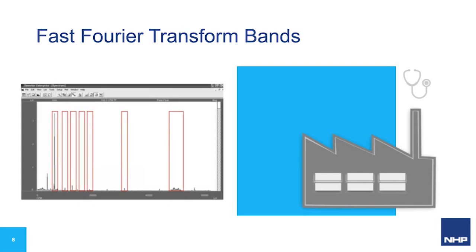Now that we're looking at a spectrum, essentially just a 2D view of the right-hand side of the 3D drawing that we showed earlier, each FFT window indicates the vibration magnitude for a specific frequency range of a measured accelerometer signal at a single point on a machine. So the displayed bands, or frequency windows, will indicate different conditions on the machine.